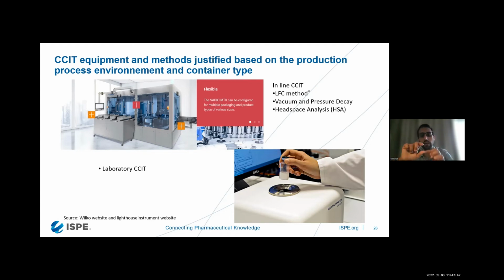But if you use, for example, headspace analysis, you don't have enough time between the process and the testing to see if there was a leakage. So for this type of process, it's better to do a laboratory test or to allow a certain time for the exchange of gases before performing your CCIT test.